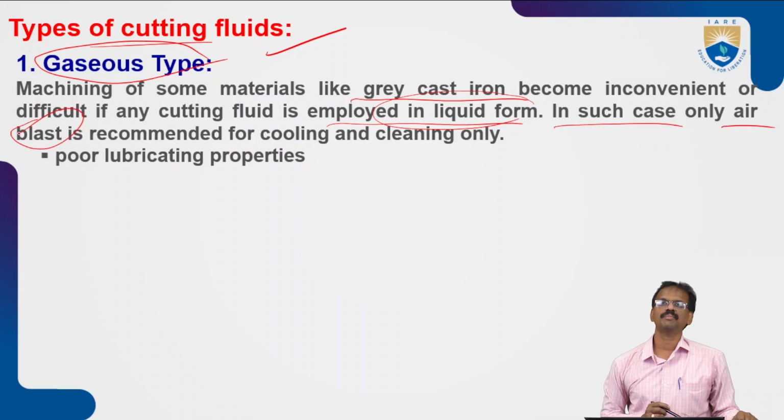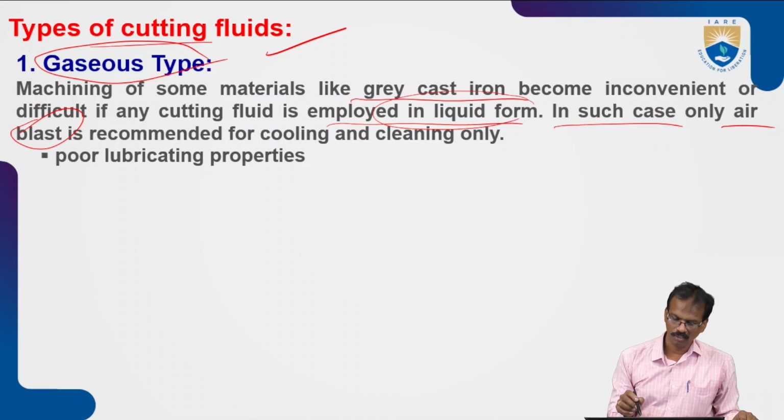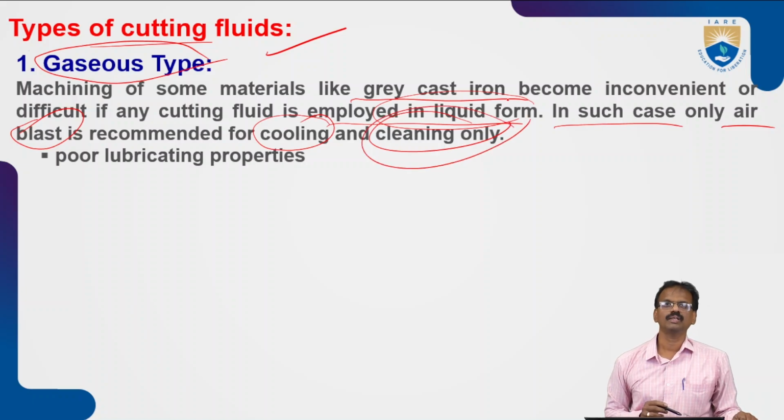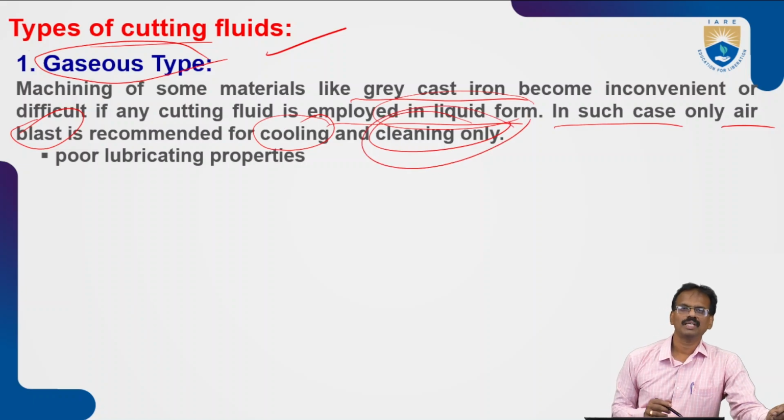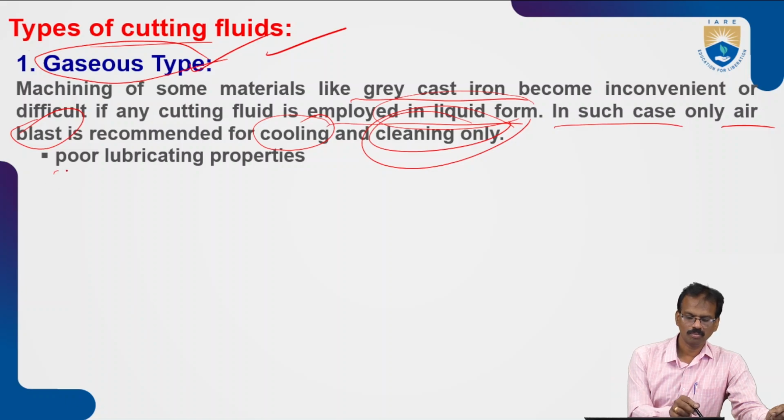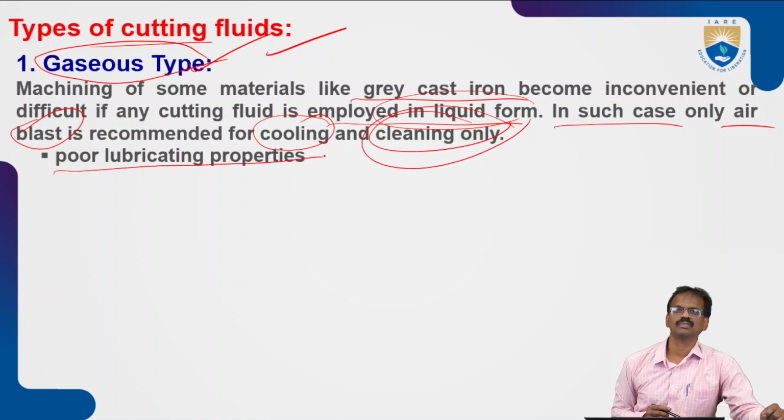So in such occasional cases, only air blast is recommended for cooling and cleaning only. Okay, so for the cooling purpose and the cleaning purpose also. But gaseous type has very poor lubricating properties. So it cannot reduce the frictional coefficient between the workpiece and the tool bit.